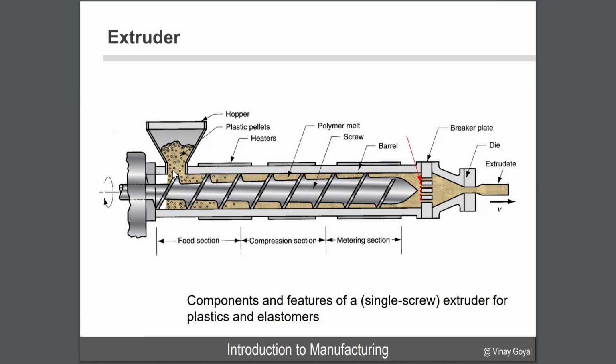And as I'm extruding this material through this tube, it works similar to a drill, where I'm rotating this and the material is getting pushed through. Think of this as a conveyor belt. The material is getting pushed and the voids are getting reduced. We call the center section here a screw, and that screw acts to move the material along. This metal encasing is called the barrel. This first section is called the feed section, then we have the compression section, and then we have the metering section.